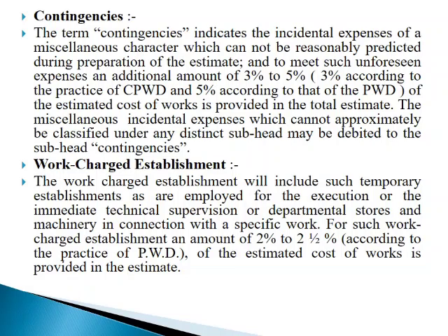This is also the work charged establishment. Work charged establishment includes temporary establishment employed for the immediate technical supervision of the execution, or for departmental stores or machinery in connection with a specific work. For such work charged establishment, an amount of 2 to 2.5% of the estimated cost of work, according to the practice of PWD engineers, is provided in the estimate.